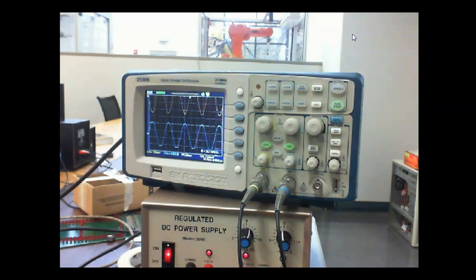Y'all understand why? Because I'm taking the output across the transistor, and it's 180 degrees out of phase. But as long as I stay within these boundaries, I'm fine. You can hear people that have poorly designed stereos. One thing, they might be overdriving it. They're putting an input signal into it, and they don't have enough voltage to work with, right? Another thing is they don't do impedance matching.